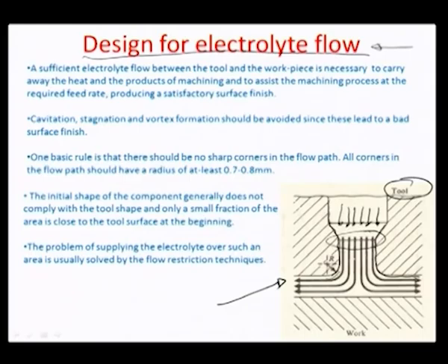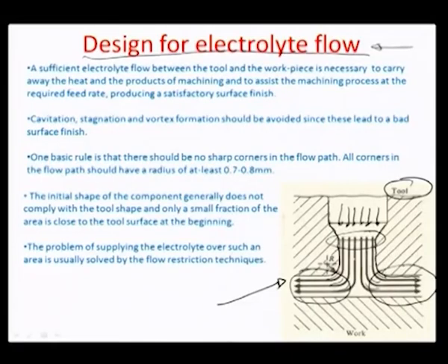gives an option that the electrolyte can be pumped in, and you can see that because this gap is very small and the curvature here is smooth, it makes the electrolyte flow in streamline shapes. These are very small gaps, meaning that sometimes the Reynolds number is very low because it is dominated by the effective diameter, and it is a micro scale phenomenon. So almost always the flows are laminar or creeping in such gaps.